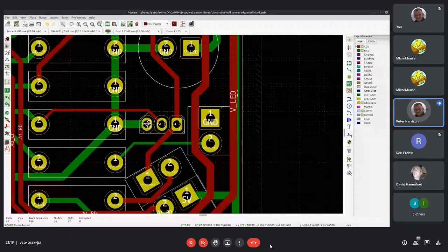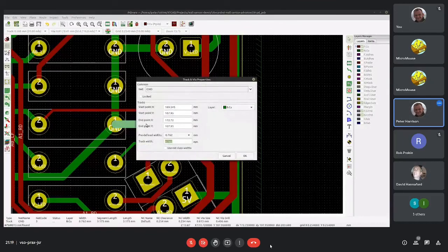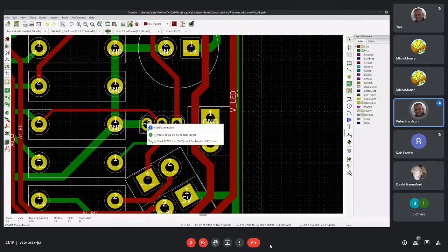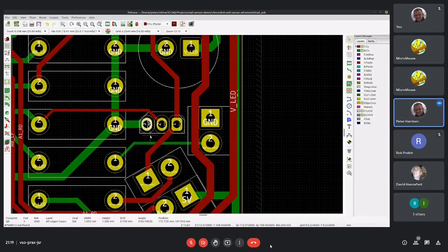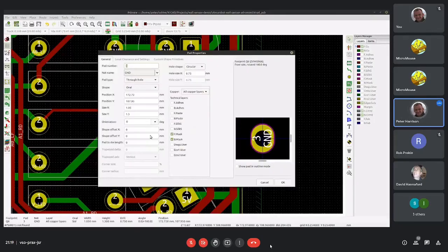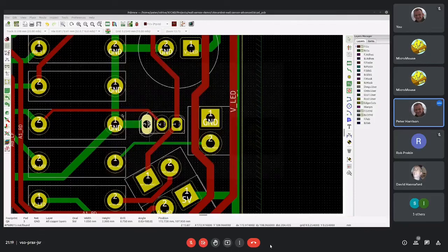The copy that goes into the net list is separate. So I can, let's see if I get this right now. That's a net, don't want the net, want the pad, edit the pad. Now I'm editing just that pad on just that component, right? And so it's currently 1.3 millimeters high. I like it 2 millimeters high, and there it is, sorted out.